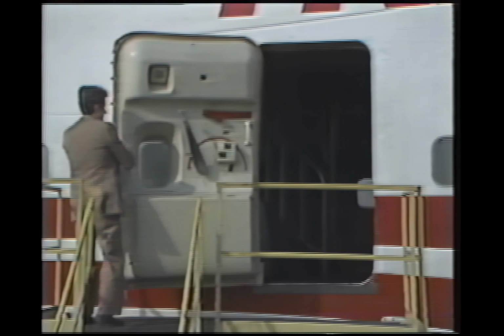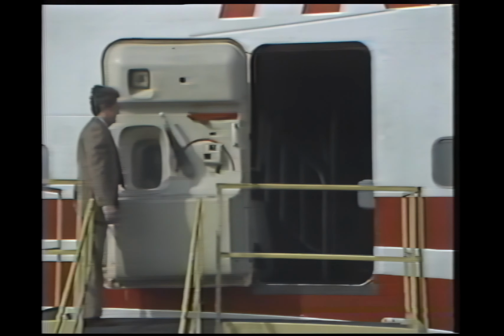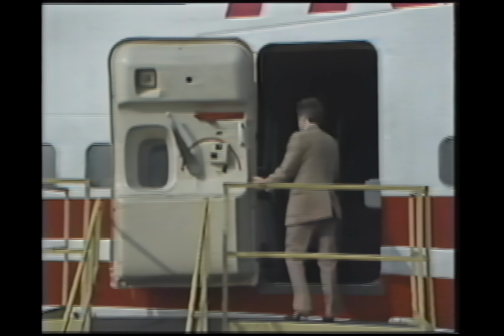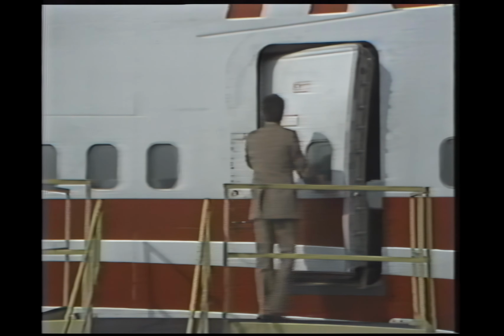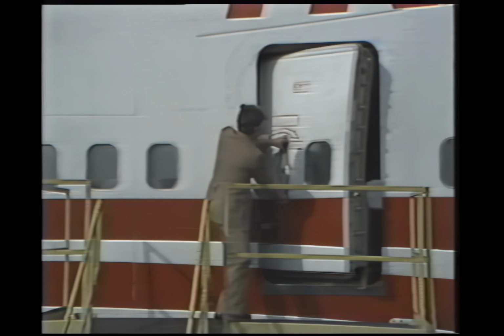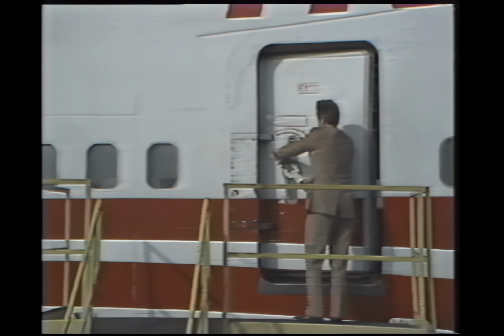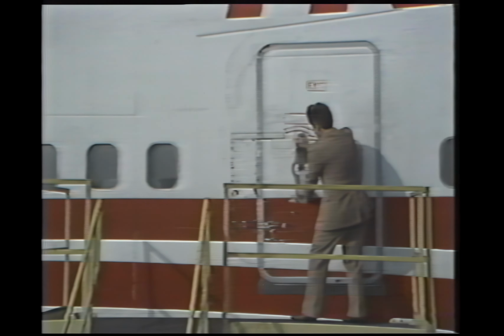A gust lock will hold the door in the open position. To close the door, lift up on the gust lock and pull the door toward the closed position. Pull outward on the handles to the extended position. Hold the handles in the extended position and push inward on the door until it stops. Rotate the handles until the door is closed and restow the handles.